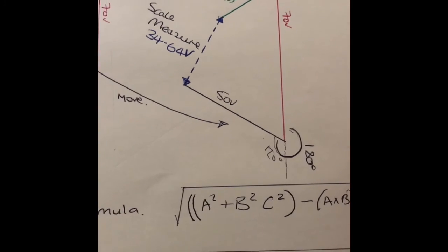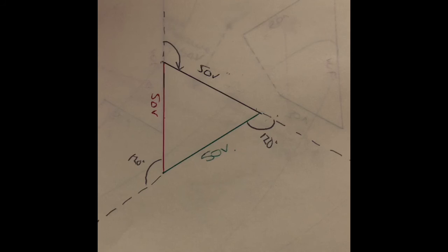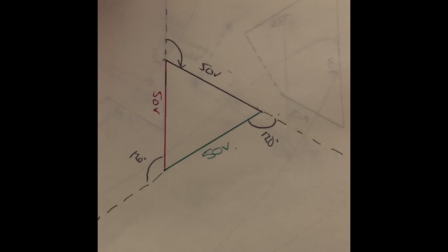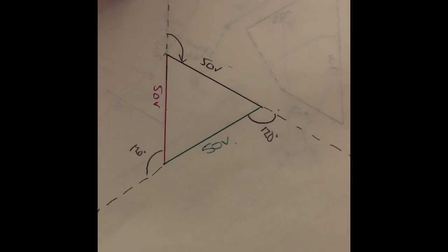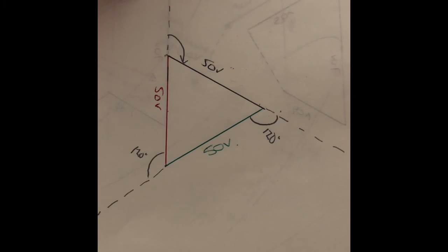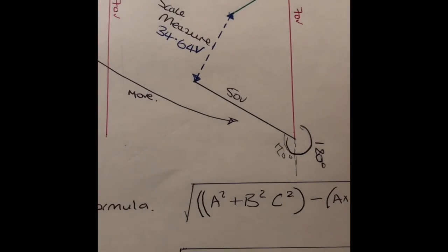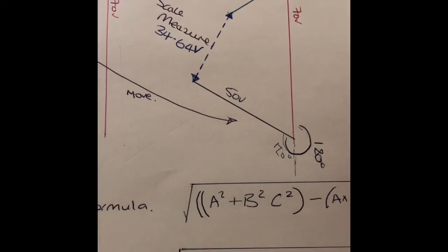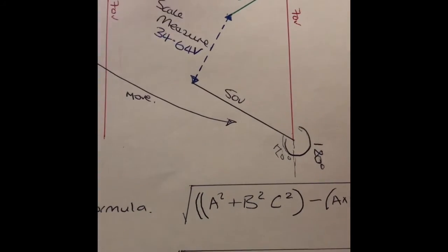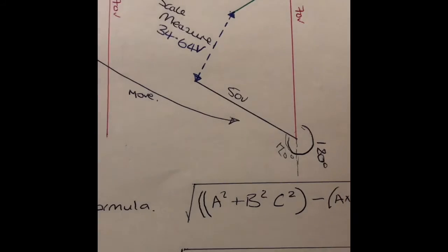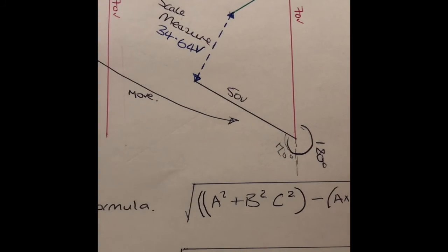So again, method 1, I'm using a protractor and measuring all of this out, and then scaling it to make it easier to understand. Method 2, of just transferring each of the lines and interconnecting them to see any resultant forces and taking a scale measurement from that, would be again another good method.